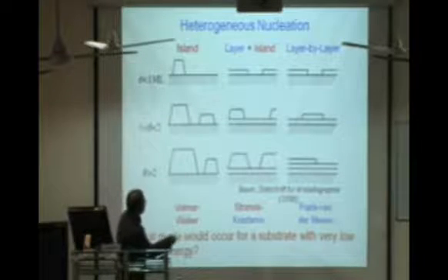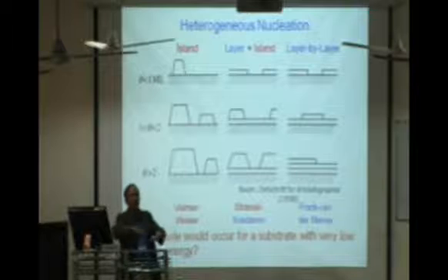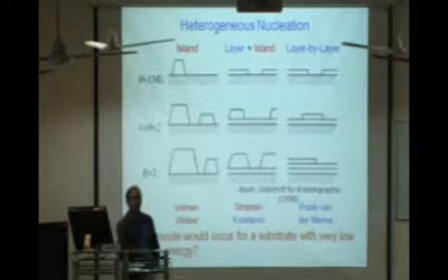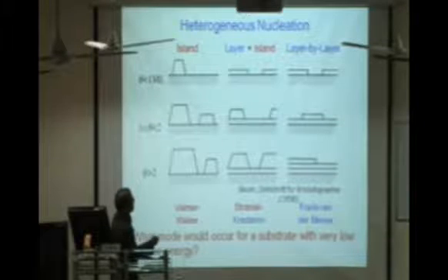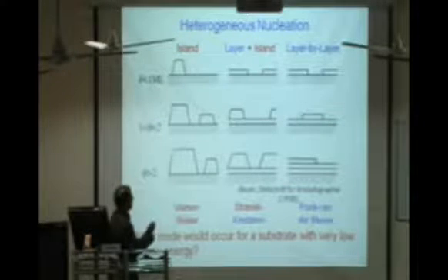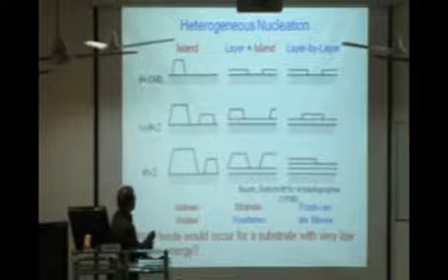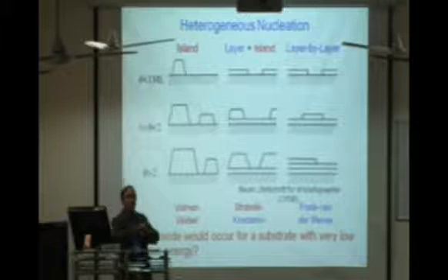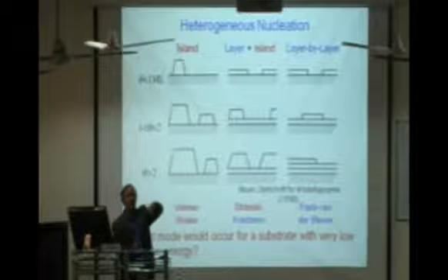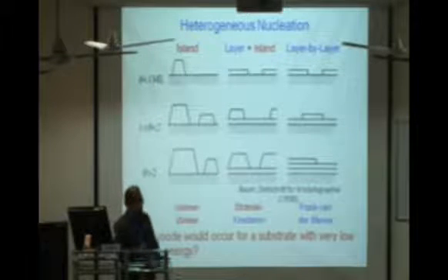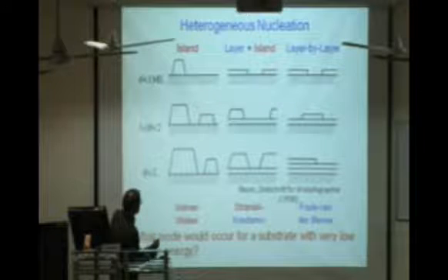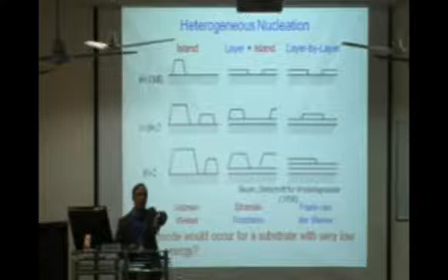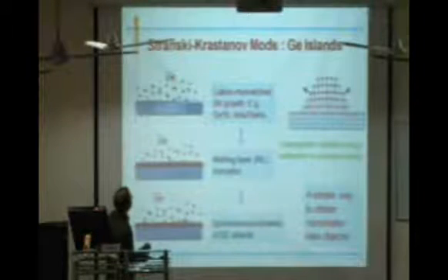In some cases, it goes layer by layer, just like water on a glass plate. So it's a perfectly two-dimensional growth. This is typically used for electronic devices or making the epitaxial layer. But there is something in between. If you grow a lattice mismatched semiconductor thin film layer on a substrate, initially it spreads. But since there is lattice mismatch, strain builds up, and this strain changes the growth mode from 2 dimensions to 3 dimensions. So they make the so-called quantum dots by what is called, in fact I have shown almost the same thing here.